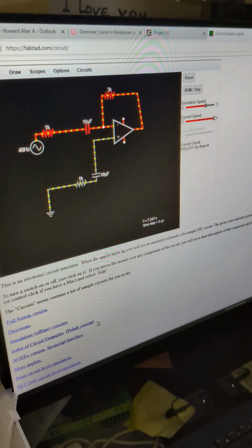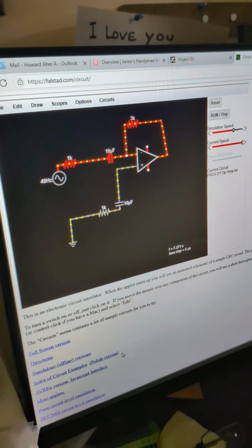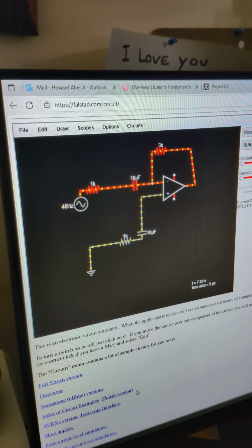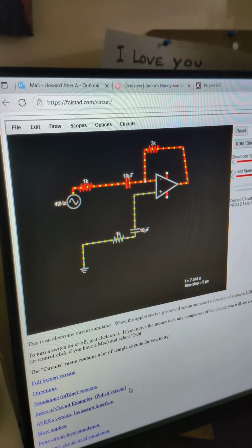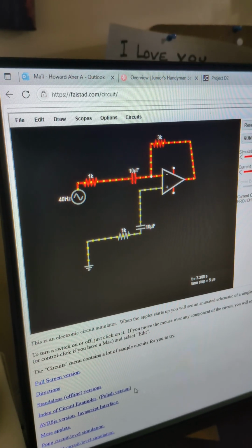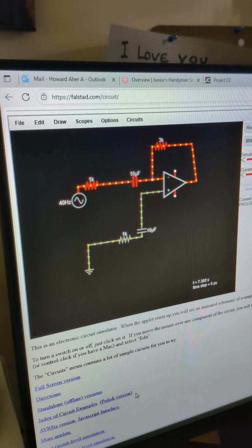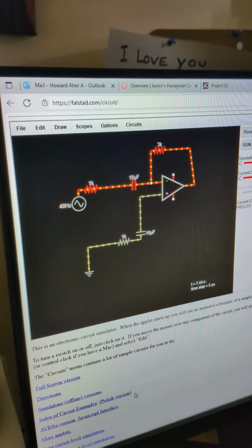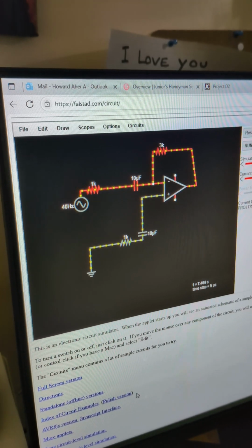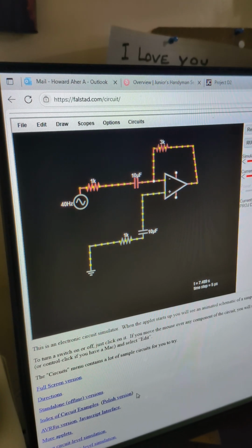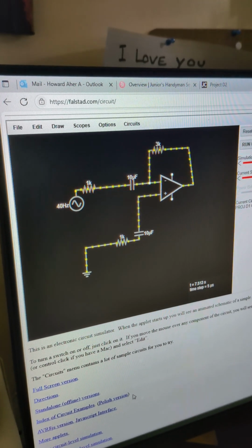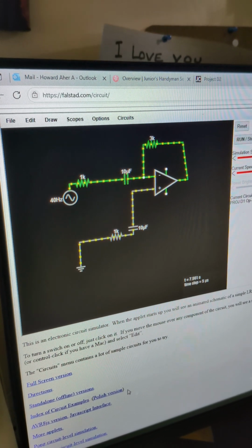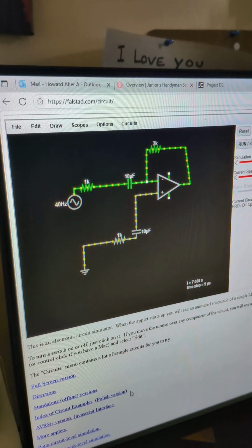This is Project D2. Question one, what is an op-amp? An operational amplifier, or op-amp, is an integrated circuit (IC) that amplifies the difference between two input voltages. It functions by using this voltage difference in an internal high gain to drive the output to a voltage that reflects the amplified difference, utilizing external feedback components like resistors to precisely control the gain and behavior of the circuit.